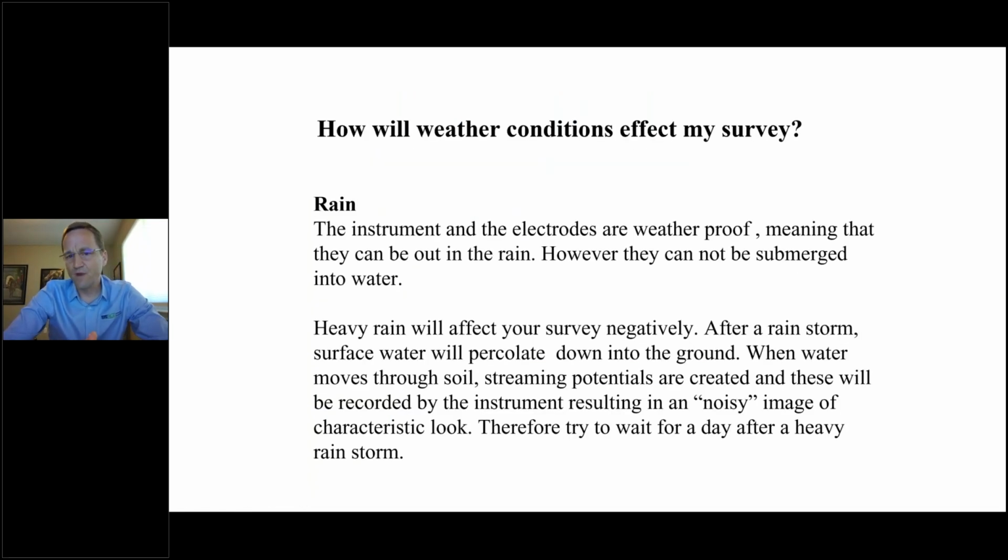That's important. Rain, not leaving. So the instrument runs these high signal levels, and it is hermetically sealed, but it's getting very hot. And if it's rain, there's cold, there's condensation, there's all kinds of things. And there are desiccant packs inside the Super Sting and the Mini Sting, but they can get overwhelmed sometimes.